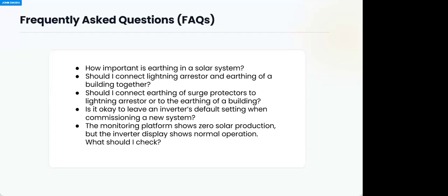Some people don't like the beep when the grid comes, they don't like that noise that it makes to alert you. So it's optional. You can go there. If the client doesn't want it, you tell the client the implication. If you don't want it, then you won't know when grid comes. You may know through other ways, but the inverter will not tell you that grid has come or solar has come or anything. You can turn it off.